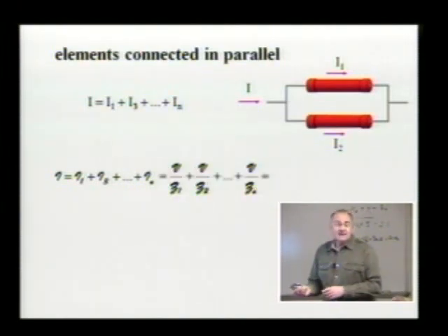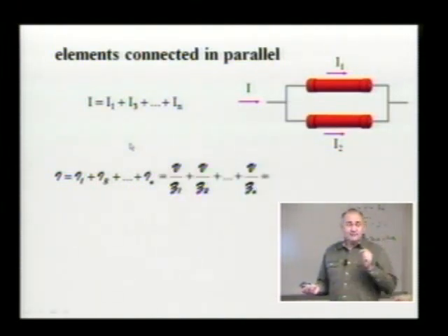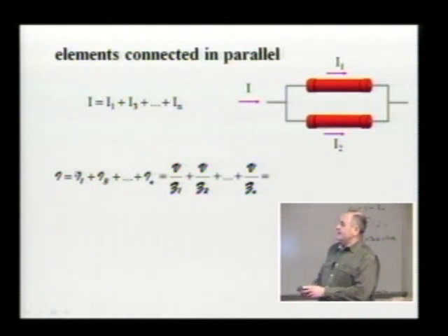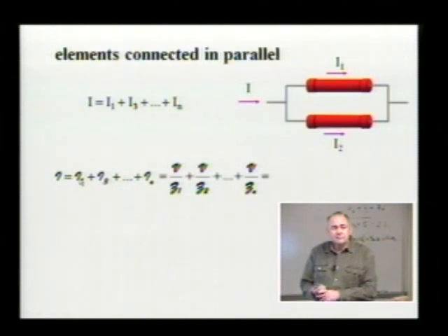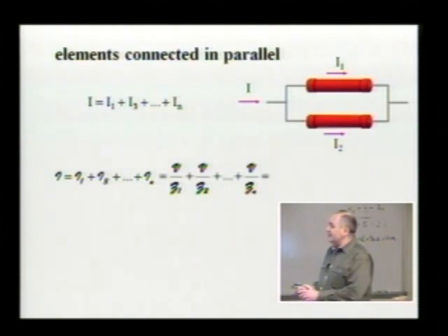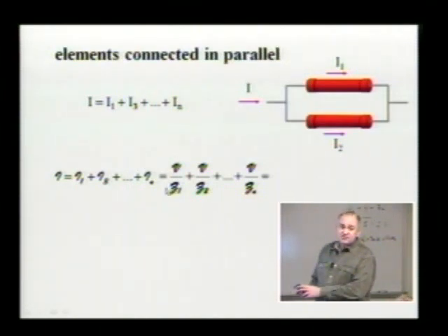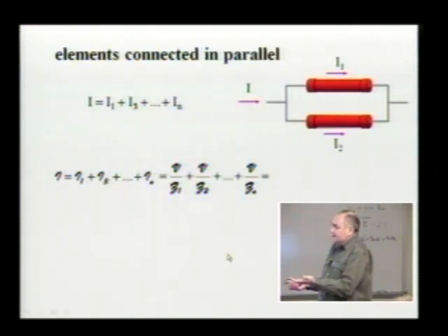All right. Now, according to the definition of complex impedance, I can recognize that this derivation is identical to what we did for resistors connected in parallel, because previously we had a real current over here and replaced it by the voltage across the resistor divided by the resistance of the resistor. Now I have an arbitrary element and complex values.